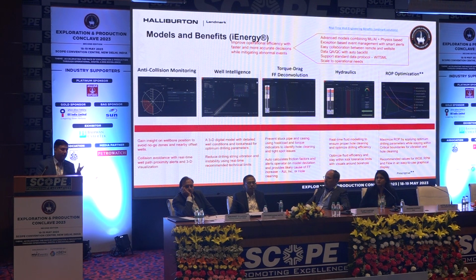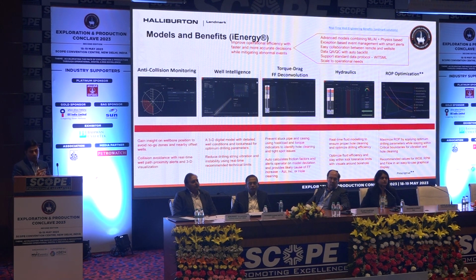Second one is about the torque and drag and the friction factor deconvolution. Like we know, torque and drag is available. Torque, you monitor on the rig site and also in some real-time operation centers. But this model will help you in doing the torque and drag analysis while drilling. Along with it, you can do reaming in, reaming out, I mean back reaming, and washing up, washing down. Also, you can do some kind of calibrations so that you can adjust the friction factor so that you will minimize the unstable borehole conditions.